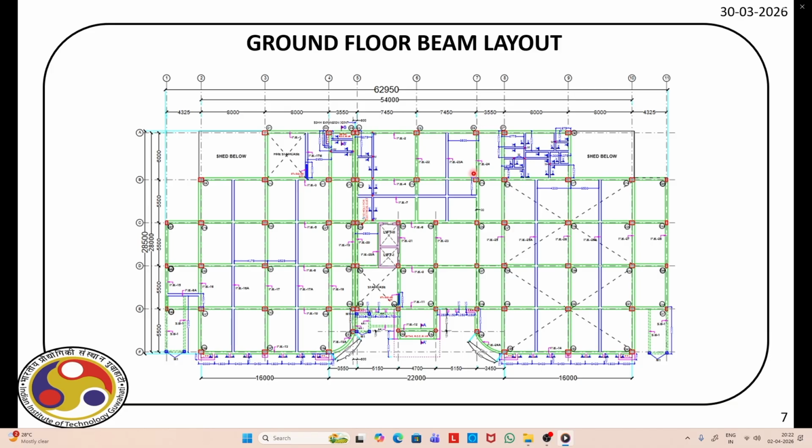In fact, those offsets also introduce additional moments over the column, and if you recall, at the design stage we discussed how these bending moments are developed at the columns, and in the second lecture this week we discussed the modeling of columns with biaxial bending. Now as you can see, we will develop the beam model. We will use a 3D beam element for the complete modeling of this structure, and using that beam element we will completely solve the frame structure.